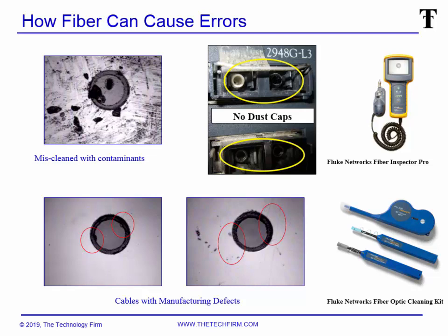If you have some fiber optics, please do not use your shirt to clean your fiber optic cables. Do not breathe on it and then wipe it on your shirt. This is what the fiber looks like when you do that. There's a picture of that, and you can see the actual fibers from your polyester cheap shirt and little gobs of your breakfast stuck all over the end of the fiber.